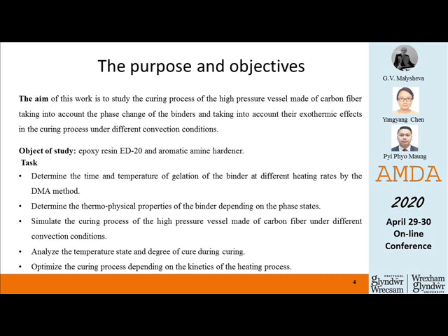I'm going to examine this topic in the following order. First, the experimental approach. Second, the theoretical approach. In the experimental approach, heat capacity and thermal conductivity of resins were evaluated in the curing process for liquid, gel, and solid state. In the theoretical part, the simulation of curing process was carried out by taking into account the change in the aggregative state of the binder in the process of its curing.